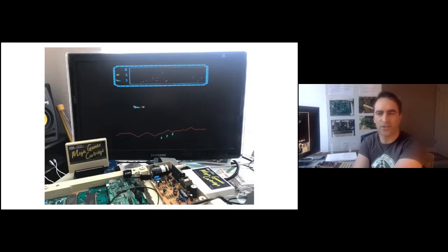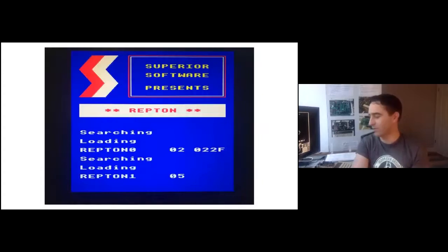So the next thing to get working was the cassette port, which actually wasn't that much work. I'd seen some notes from Hoglet about the difficulty of getting it working if you have the cassette input going straight into a GPIO. So I put a comparator instead, and I had it analog coupled through it. Actually, I think it's coupled through a capacitor on the outside, and so I had a biasing circuit.